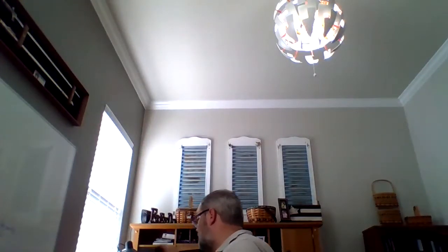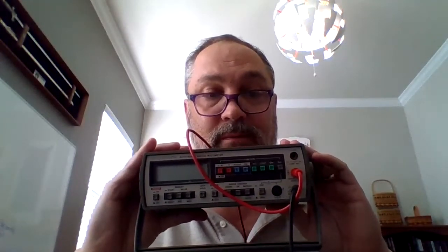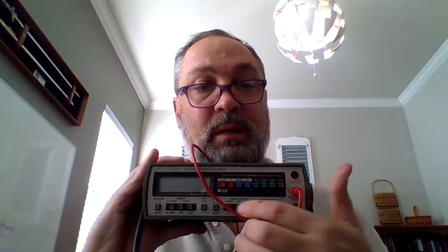Right here is my personal multimeter that I use quite a bit. It's called a bench style multimeter. You'll notice it still has the leads plugging in over here. You notice I hardly ever use the amperage one, but it can measure actually quite a bit more. But I always set it up to measure voltage or resistance, and I almost always keep it on DC. There are a few times that I'll make measurements on AC. You will never need to make measurements on AC as part of Circuit Lab. It's just too dangerous.